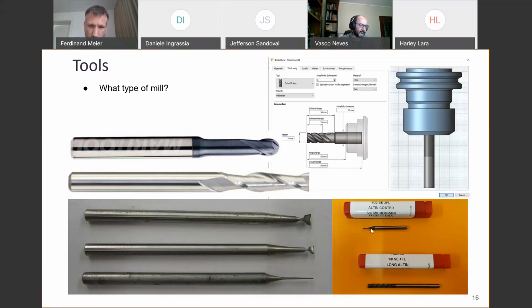With this one, you have to be very careful, and you can't mill next to your side walls. You can basically only mill in places where there's no vertical walls or only very short ones. But this combination already allows you to do a wide range of molds. If you have anything longer or thinner, even better.